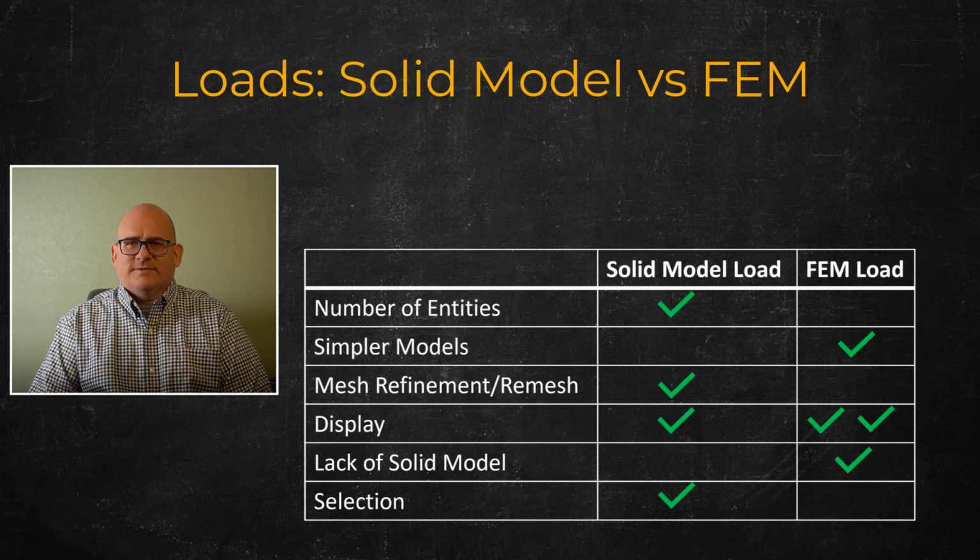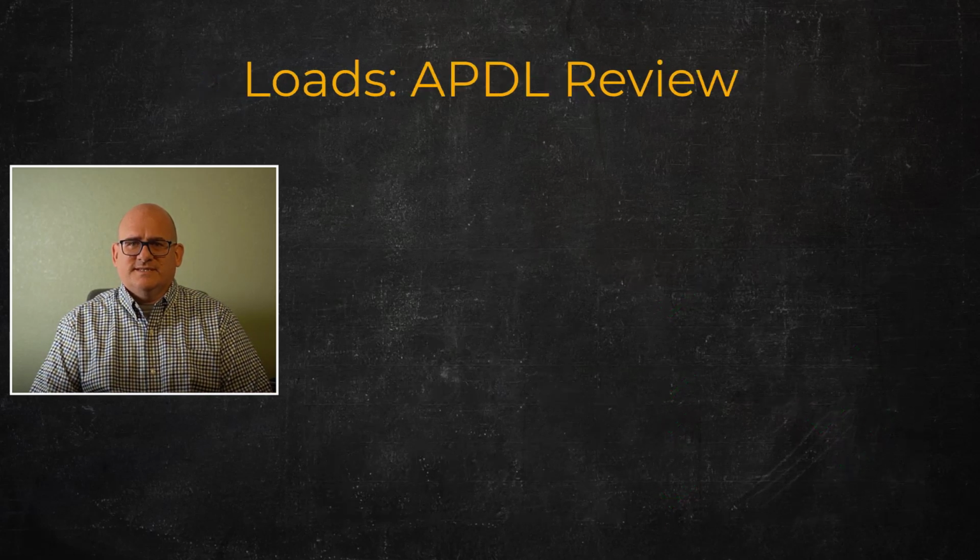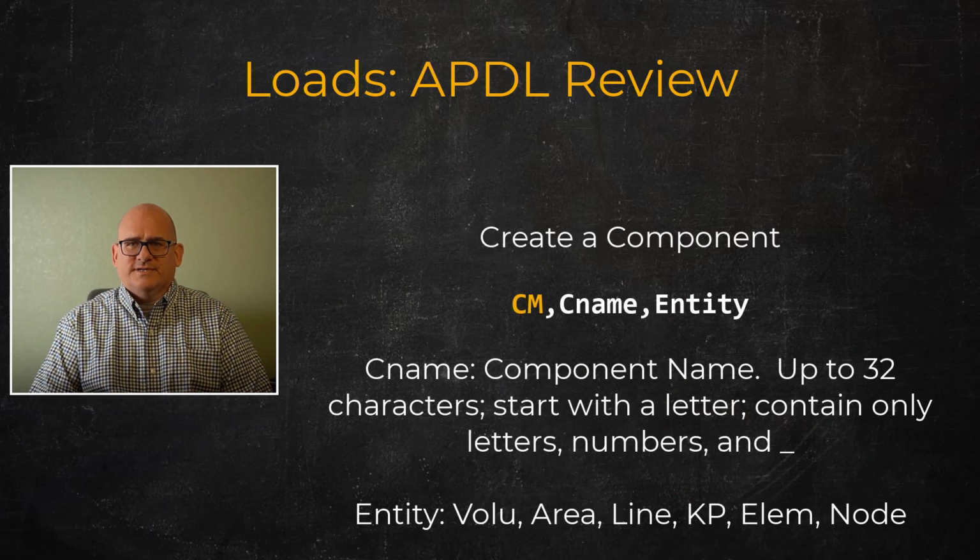Finite element loads are typically used if we don't have the solid model geometry. For example, when importing a mesh from another preprocessor like ANSYS Mechanical, only the finite element information is included, so applying the loads directly to the nodes and elements is necessary. Mechanical APDL components, which were introduced in the solid modeling and meshing lesson and discussed further in the select logic lesson, are very useful when working with finite element based loads, as the item, or the node and element IDs, that the load is applied to can often be a component name.